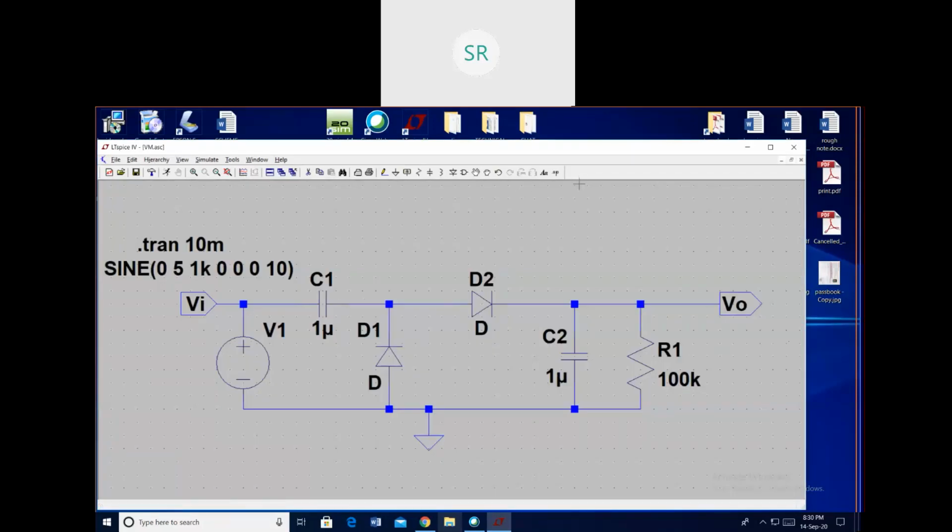So now what I will do is reduce this RC time constant a bit. This R, which was 100K, now I'll make it 10K or 1K itself. Let us see, if I make it 1K, what will happen. I want RC should be much greater than T. Now this is not satisfied. Let us see whether the output voltage is doubled. So save and run this now.